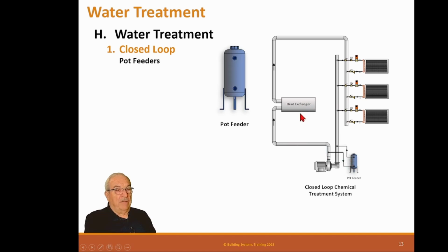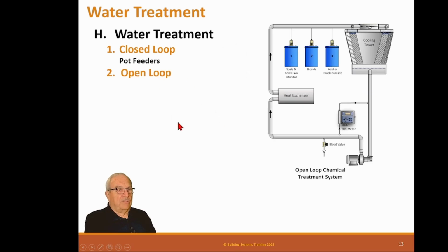Then every 6 months or every year, you check it again and add some more, because if this has leaks or they've changed something, fresh water will actually wash some of the passivation away, so you have to repassivate things over time. Pot feeders come in 2.5 gallon and 5 gallon size. Some have filters in them, some don't.